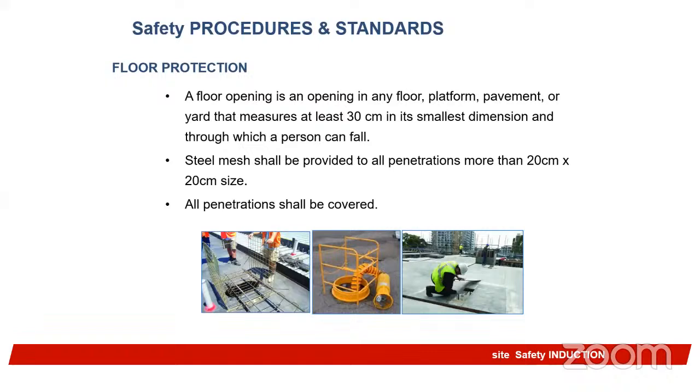It can be as simple as a scaffold installed, what we do most times, or proper edge protection like we have it here. Steel mesh shall be provided in this particular one. Steel mesh can be provided to all penetrations more than 20 centimeters by 20 centimeters in size. All penetrations should be covered. You should make sure that all edges, all floors, all openings should always be covered at all points in time.